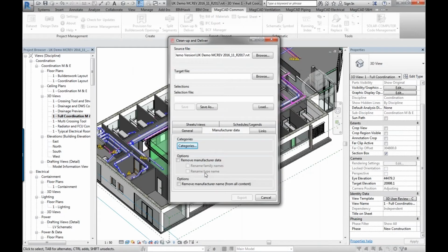And then down here you can choose whether you want this model to be preserved with the worksets, or discard worksets, audit, and you can delete or maintain revisions, for Revit revisions, that is. Compact the file and then leave it open at the end if you want to purge anything for yourself. So that's one setting. And it's interesting, you can actually strip out manufacturer's data for any of those products, so you can choose which products you want to strip out. So it could be mechanical equipment, plumbing fixtures, whatever it is.